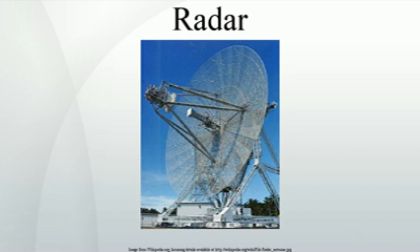This beam configuration allows the radar operator to detect an aircraft at a specific azimuth but at an indeterminate height. Conversely, so-called nodder height-finding radars use a dish with a narrow vertical beam width and wide azimuthal beam width to detect an aircraft at a specific height but with low azimuthal precision.